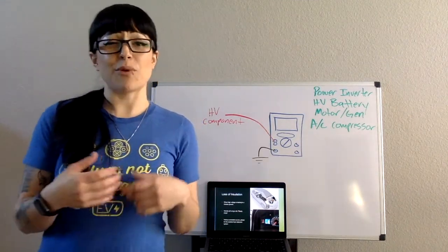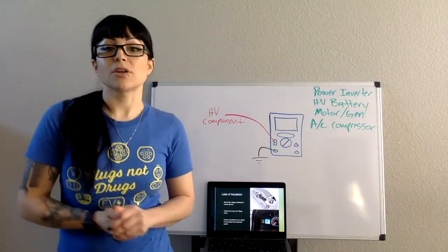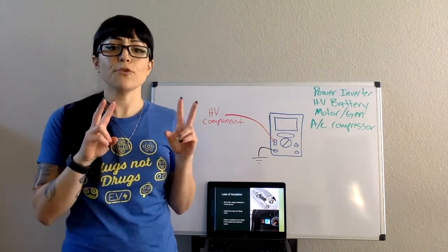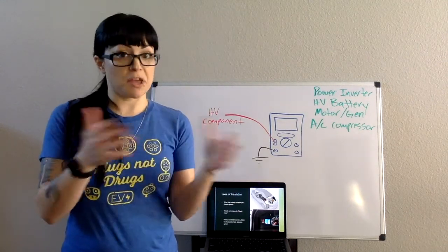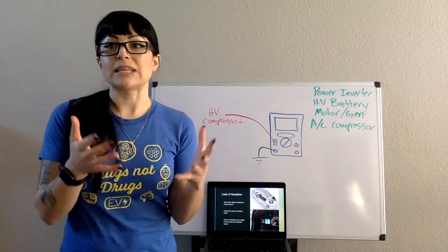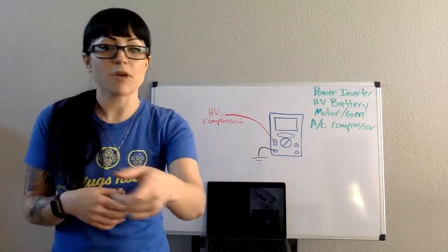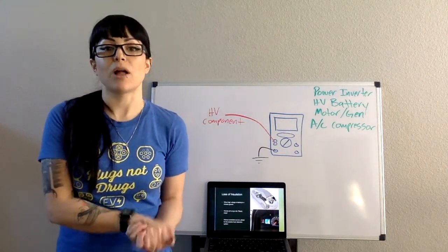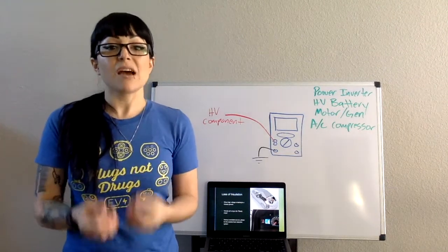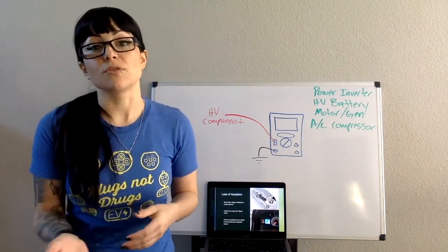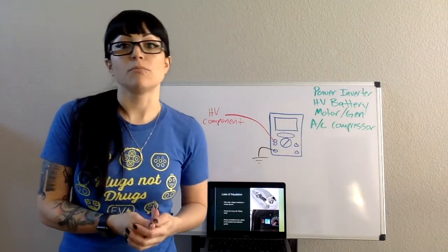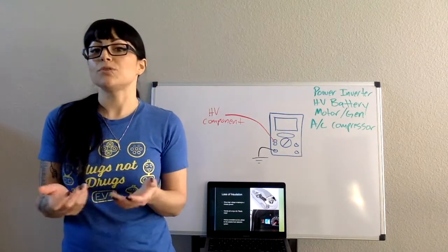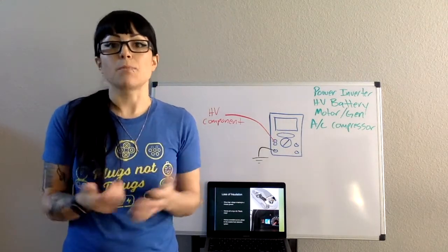And last class session that we were actually in person in, where we were talking about electrical and different types of grounds, we talked about floating grounds, right? So floating grounds mean that everything is insulated. We don't really use anything as a ground. There is a cable coming from battery positive and a cable coming from battery negative as well. Everything is insulated. So if any of that leaks out to the vehicle's chassis, engine, motor, generator, casing, anything that you could potentially touch and get hurt, that's a problem.